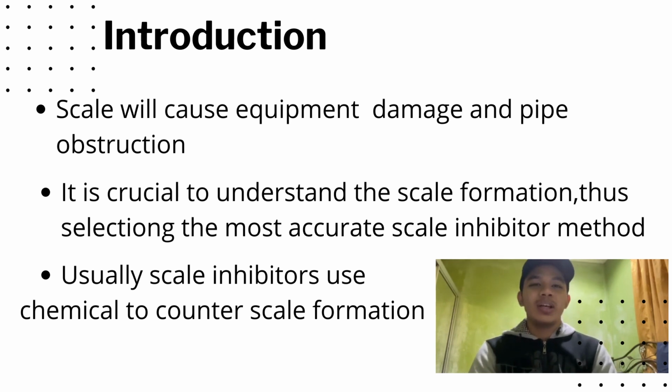It is crucial to understand the scale formation, thus selecting the most accurate scale inhibitor method. Usually, scale inhibitors use chemicals to counter the scale formation. We inject chemical to prevent the scale formation.